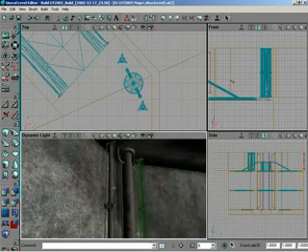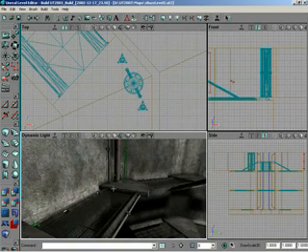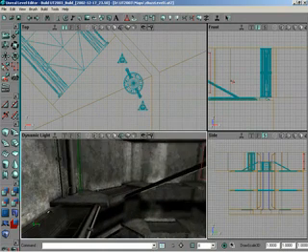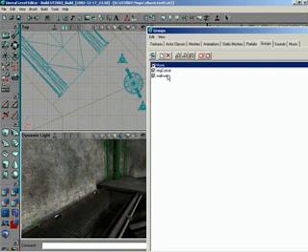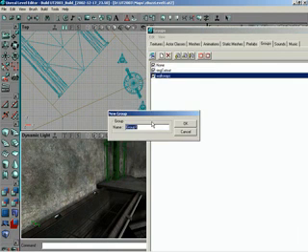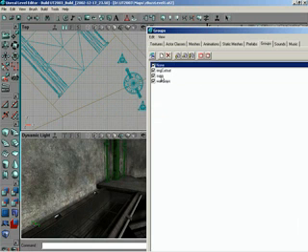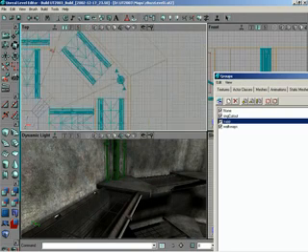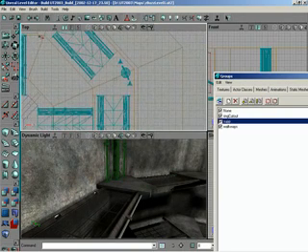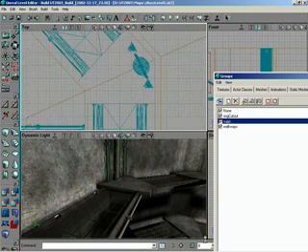Okay, so we have those supports in place. But now we need to go ahead and get 8 more of those to go all the way around. So I'm going to select those 3, bring up the groups browser again, and create a new group. We'll call this Pipe supports or something. I'll be short: SUPP. Yeah, it's very short. So I'll create that new group, select it, add those 3 pipes to that group, and then I can start duplicating. Control W, and let me center them up.